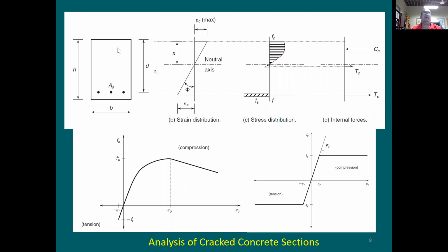Okay. This beam here is exposed to positive moment. Definition of positive moment: tension is going to be at the bottom and compression on the top. Let me draw here the strain distribution and the stress distribution. This is after cracking, because we have done it before cracking. And you know what happened before the cracking point? The stress above and below works as if you have a homogeneous section, and the reinforcing bars were not acting there. They were not triggered yet. There's no real tension force in there. But look at what happened here.